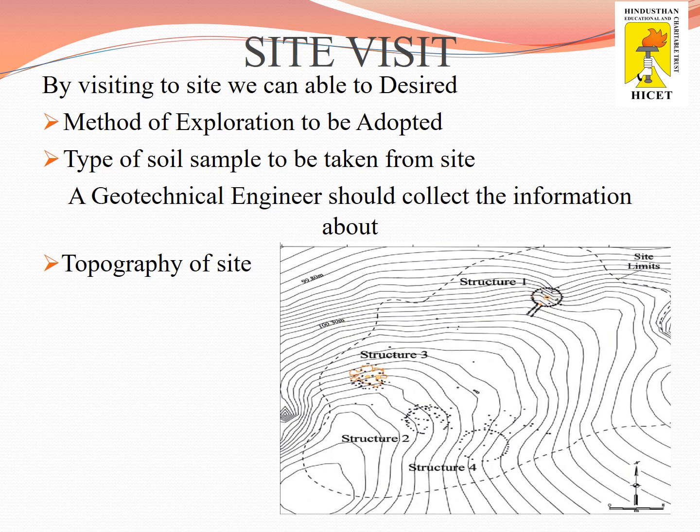Site visit is the first step of subsurface exploration. It starts with a study of maps, further programs of site investigation, method of exploration to be adopted, and the type of sample to be collected from the site.